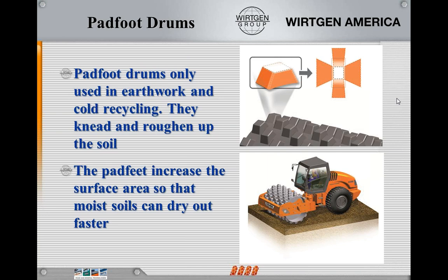By doing it, there's two things. It increases the surface area to dry out the material, but also the shape, the way it's tapered, actually squeezes the material as you compact into it with the pad foot against the other pads. So now we create a greater force of squeezing that material together, trying to get the compaction and taking out some of the moisture. But the surface area is much greater, so we can actually reduce some of the moisture that's in there.